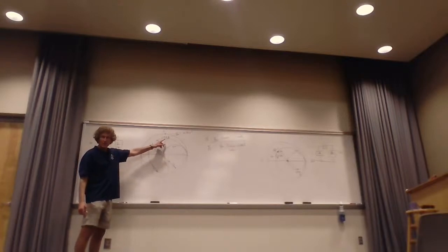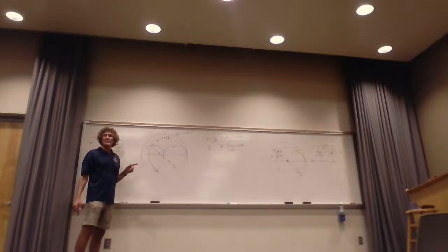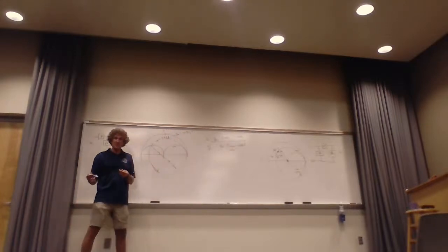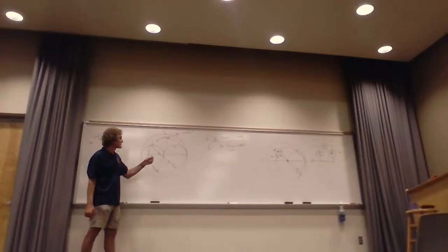If I'm moving from here to here, I'm going to be adding something that's going to reduce this value, or it's a negative j, correct, class? If I'm adding a negative j, that's a capacitor in series. And if you don't want a capacitor in series, then go right to the admittance domain.